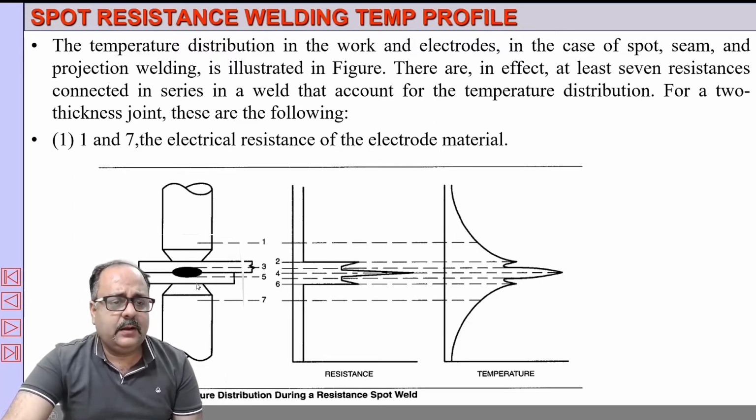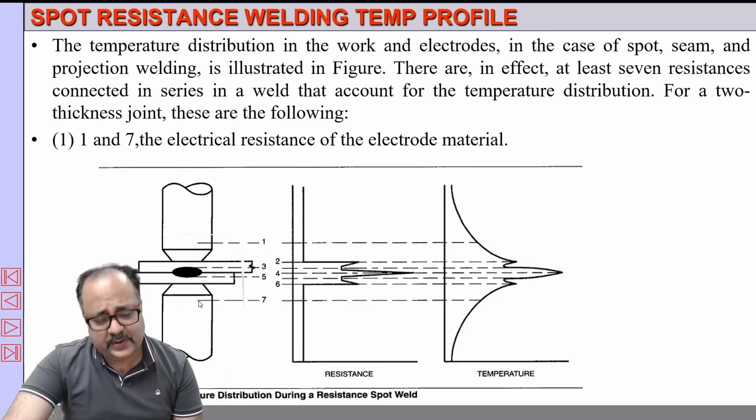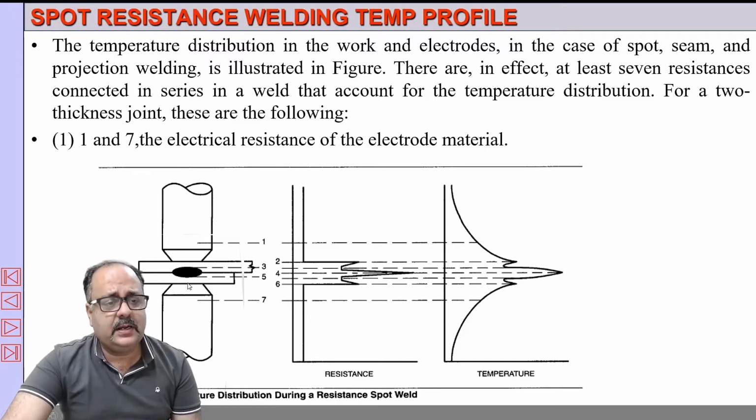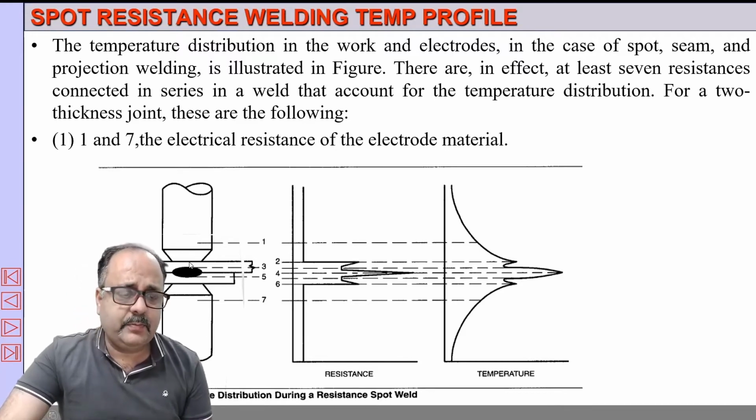However, because the heat is dissipated rapidly due to the high thermal conductivity of the copper electrode, and because this copper electrode is water cooled, the heat that is produced is dissipated, and we can lower the temperature of these two junctions. Therefore the chance of the electrode welding to the workpiece material is reduced.